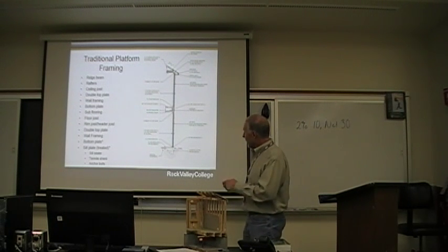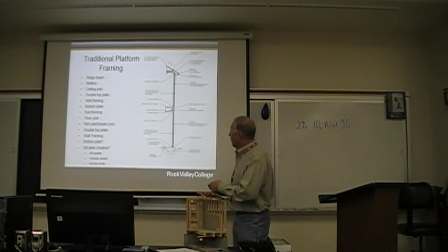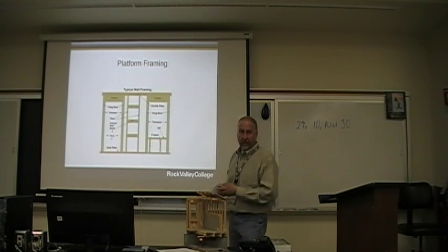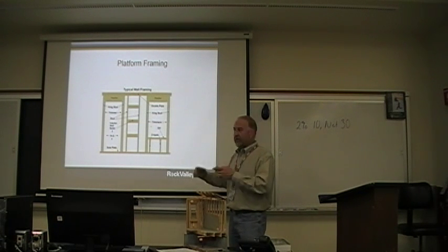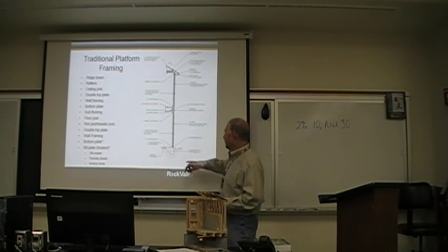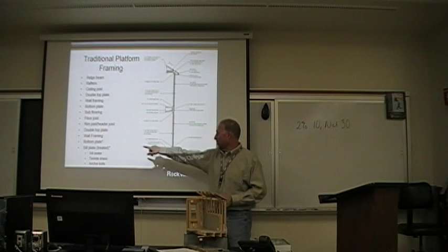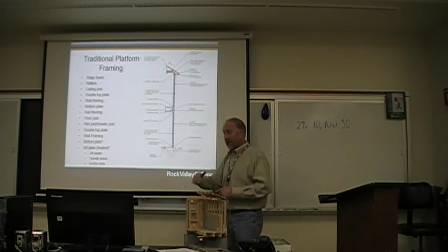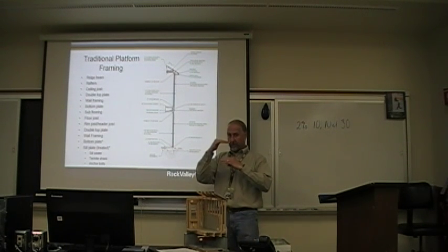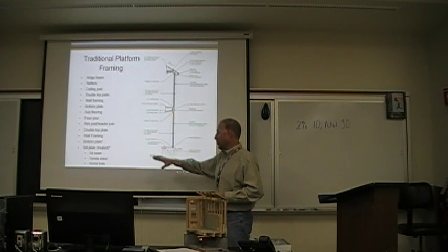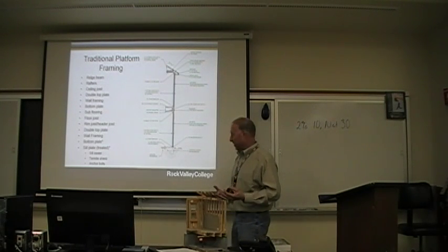Okay. Typical wall section in here. Something unique at the bottom. Typically, when you see a wall frame system like this, it's built on the deck, raised up into place. I've seen both ways where we use a sill plate, which is a bottom board. It separates the foundation from the other assembly. Okay, treated, so no, for decay.